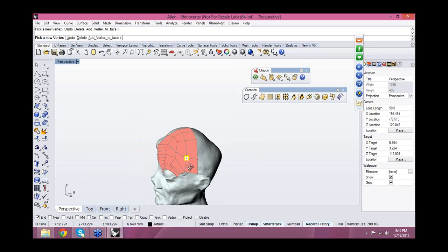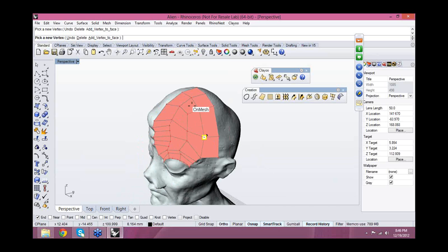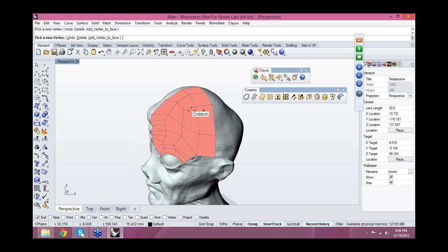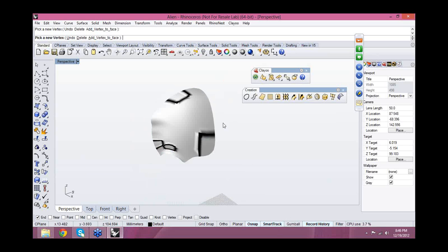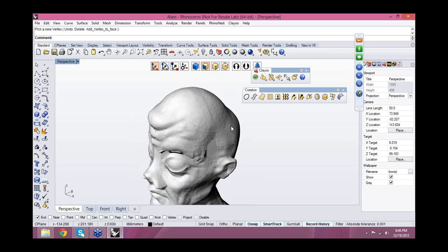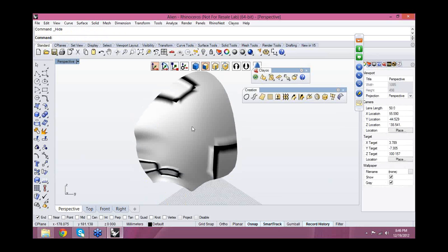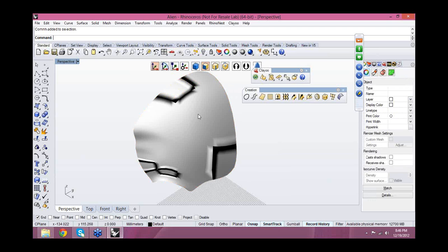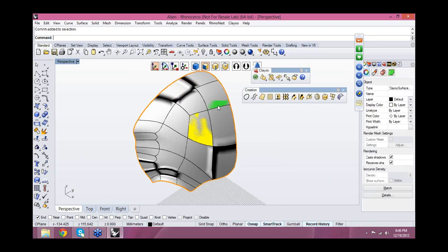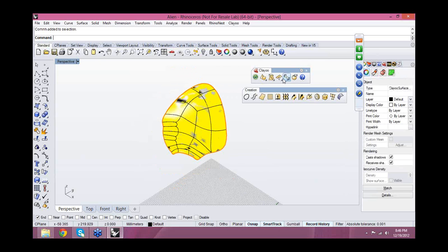Then now I have these surfaces, and then I can click the right button. Let me hide the STL. And here we have our Clayoo surface. In some cases, we will see these black areas. This is because the normals are inverted. Then it's very easy to fix. We just come here and we rebuild normals.